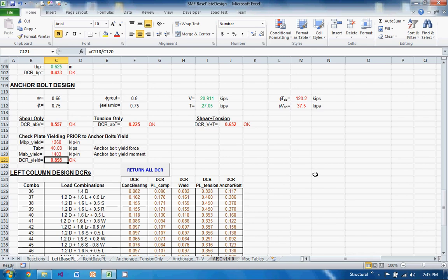Our inspector is actually rejecting it because they're going over more than what's allowed. What's allowed is typically 1/32 over the 1/16. The vendor for that frame has a bigger size, so our inspector is rejecting it. So that's base plate related, fabrication wise.